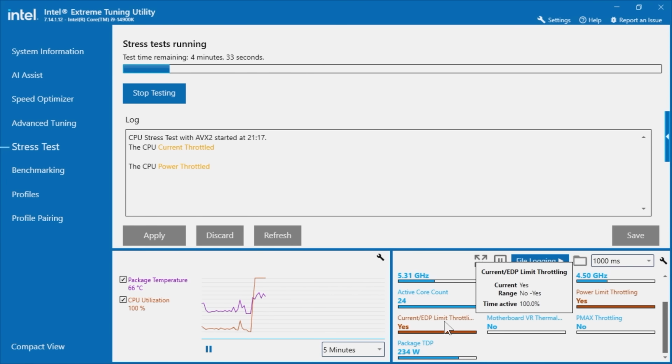So what it does is essentially modify the profile and add a profile into the actual device manager. If you were to look in device manager, look at software profiles, it actually modifies the voltage within that setting there. If you go back into your BIOS and check the undervolt application, it will remain the same. So it essentially overrides the BIOS setting on the particulars that you set within the application itself.